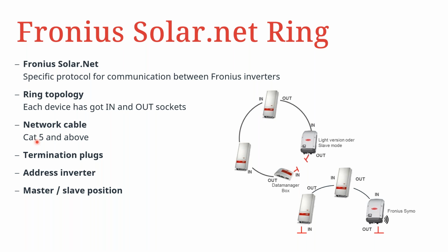It is recommended that we use Cat5 cable and above for any of these communication loops. In order to achieve this, we have in and out communication ports. All we need to do is ensure that the plugs are in the correct position, and then the loops are done from the out terminal of the first device to the in terminal of the next device. This continues until the loop is complete, and then the out stop plug of the last device is left in place.